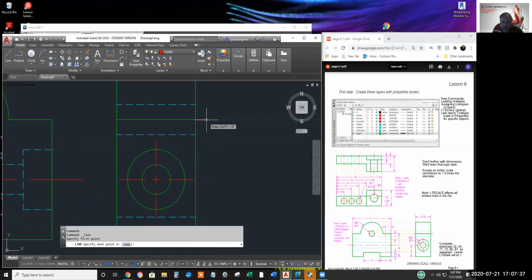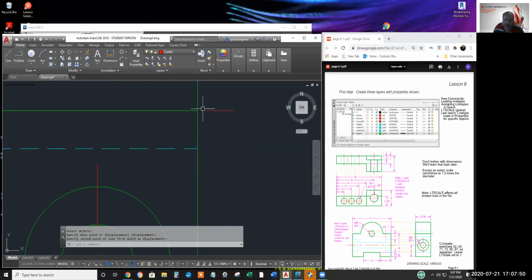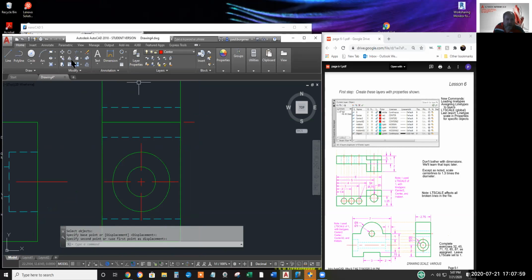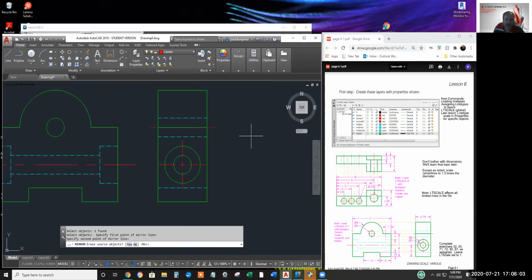I guess the 1.3 should apply, but I'm too lazy to do that. Now check it out. I'll move this guy to apply a slight white space there. And the textbooks will tell you that means there's a center line that coincides with the object line. I'll mirror that little whisker about the center line of the object line. Now I believe we're finished.